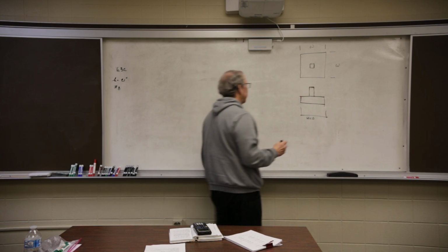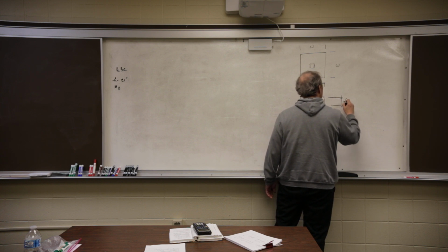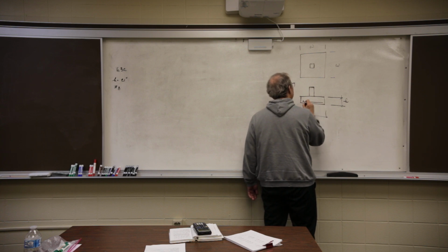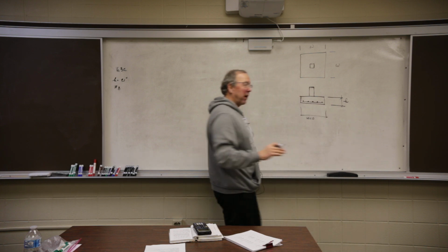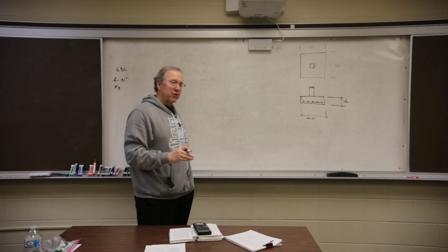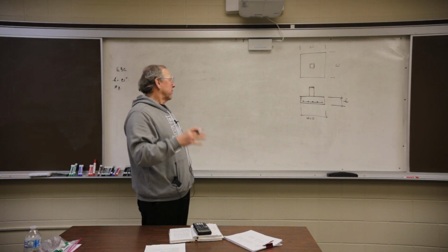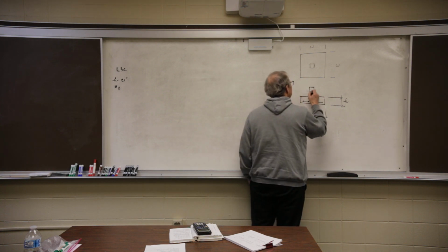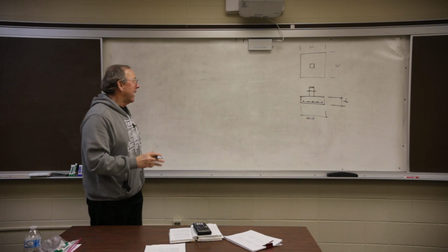And we've got the same as the last one. We've got a height, H. We've got rebar, and this time the rebar is going both directions just like before, but this time that rebar is both structural. There is no longitudinal or temperature. So it's a mat. We're going to have a mat crisscross like a waffle. And it's going to lay right in the bottom. We got the 3 inches of cover. This is going to be the size of the pedestal. That's not the wall thickness, it's the pedestal size.